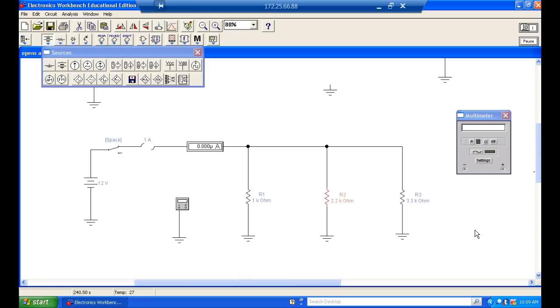Well, for NEC, 14 gauge is actually rated over 30 amps. But NEC rates it at 15. And we'll look at that.